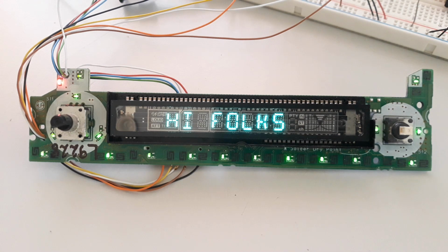To the grids and segments, a voltage of 18.5 volts. Here I'm using 5 volts DC as the logic VCC and the VFD filaments, since I'm using the Arduino platform to provide the pins for data, clock and chip enable, while maintaining the Arduino GND common to my two power sources.